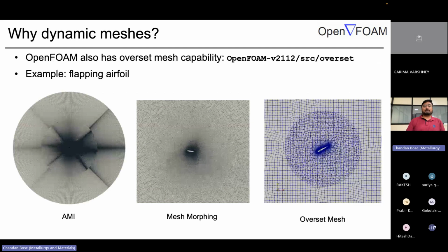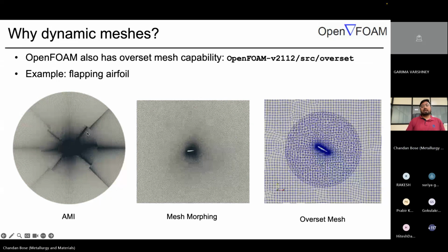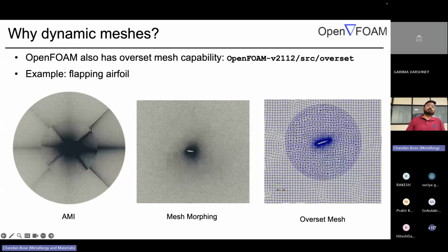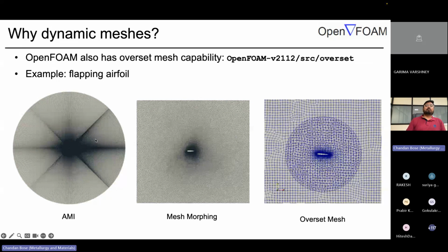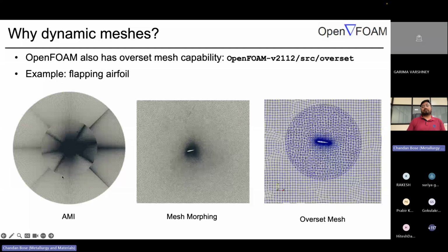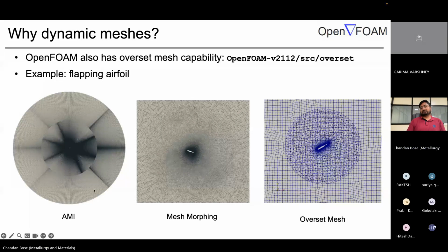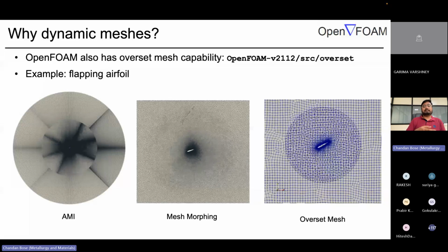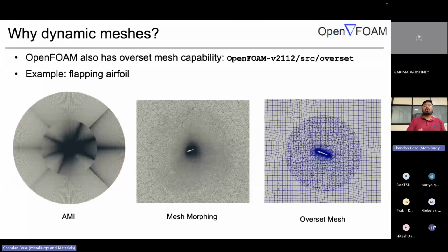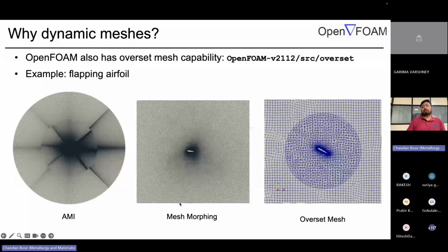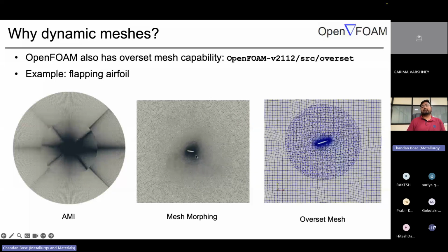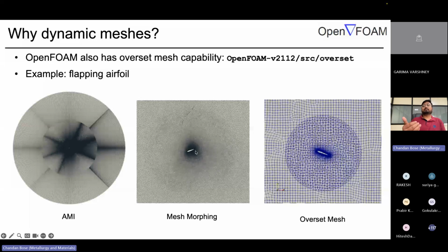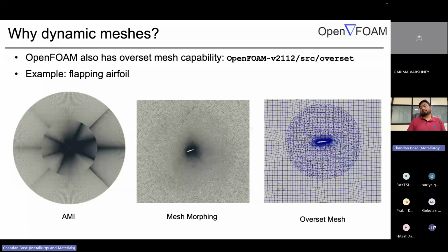So in the previous examples, in the first example of the sliding mesh, the motion type is defined over a patch, which means it is defined over a surface, which is the intersection of the two mesh regions, or it can be connected with the patch of the airfoil surface or the airfoil structure. We can apply our motion to this patch, which is the airfoil surface.